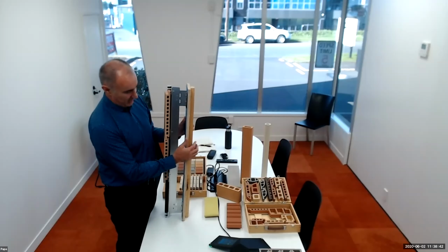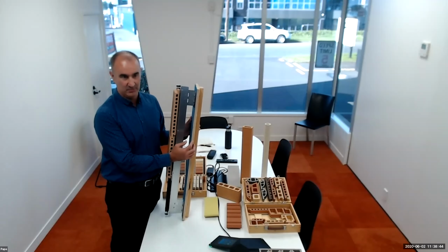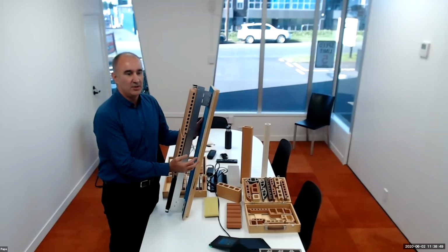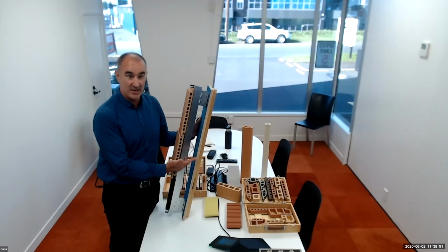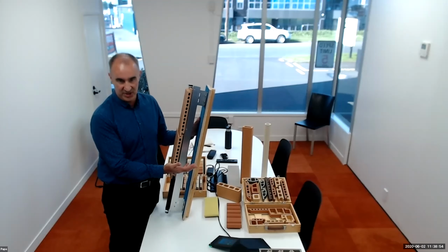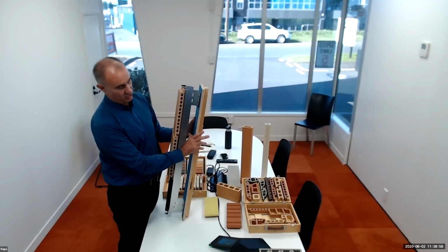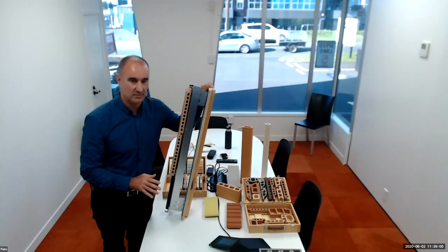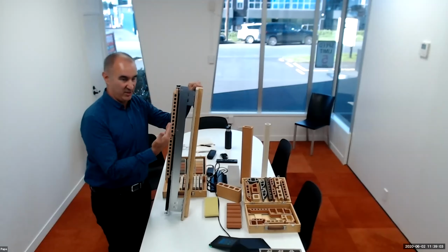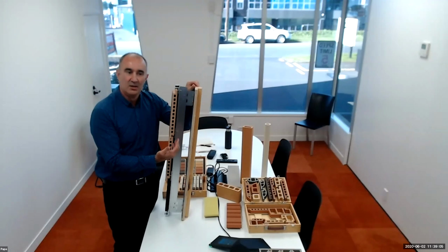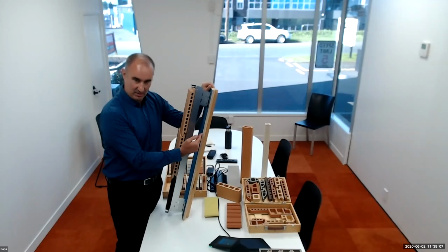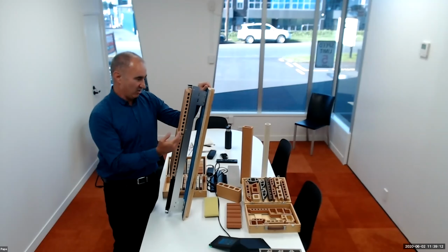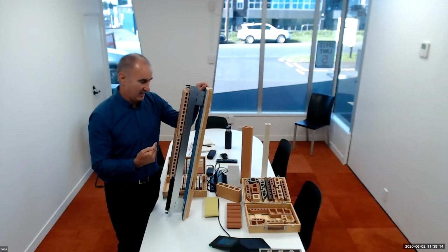This is your backing, this is your substructure. I've used plywood just purely for the fact it's more stable for a mock-up. You wouldn't get away with using plywood these days. It would need to be a compressed sheet or something like this. Then there's a wrap that goes over the top of that. That is your weather-tight layer on the building. That's what will keep everything inside nice and dry. So all of your flashing systems, etc., are taken back to that layer, right? What we then take care of is everything from that layer out.